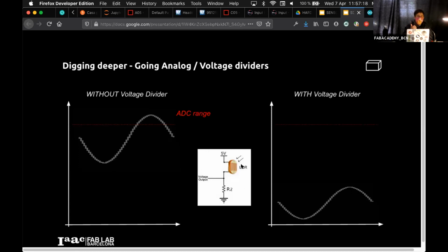Okay. This also applies not only for light resistance, but for a lot of the air quality sensors that we use in Smart Citizen that basically change their resistance when there's pollution here. So the electrical capability or the resistance of the sensor changes because there's some sort of pollutant. We measure that resistance and we know that some resistance equals some concentration. Then by only measuring the voltage with this circuit, you are able to determine however much concentration there is in the air. Okay.